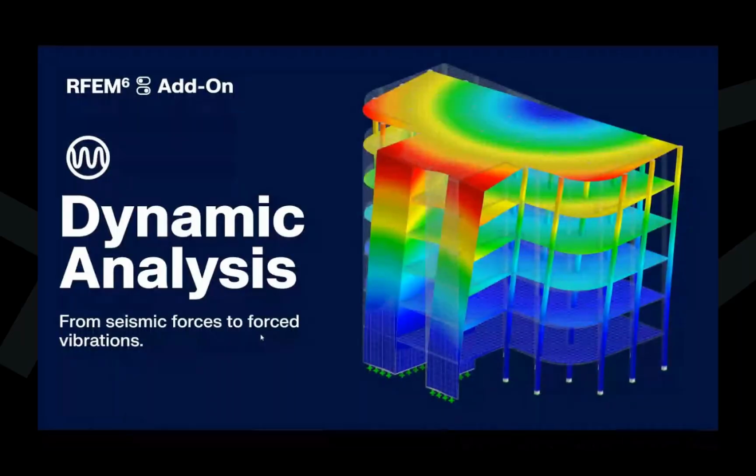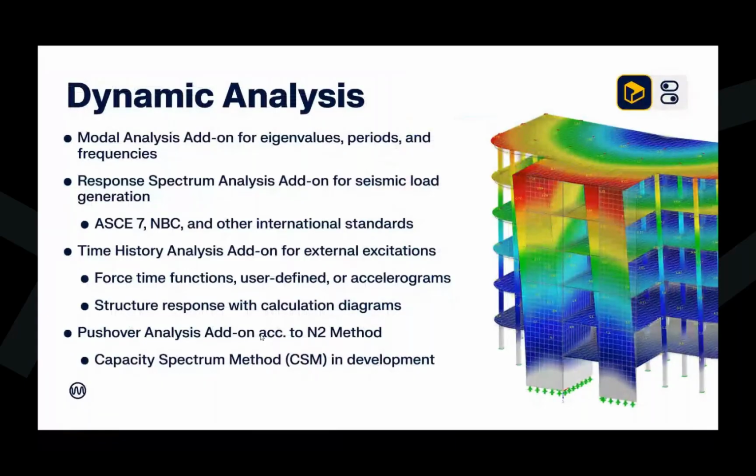Moving on to dynamic analysis. So we have several different add-ons depending on the dynamic analysis needs. So everything from seismic forces to forced vibrations. So we begin with our first add-on, the modal analysis. And this will take our structure and carry out this eigenvalue analysis to determine the natural periods, frequencies, and mode shapes, accelerations. This add-on is always a prerequisite before we can utilize any of the other dynamic add-ons listed here.